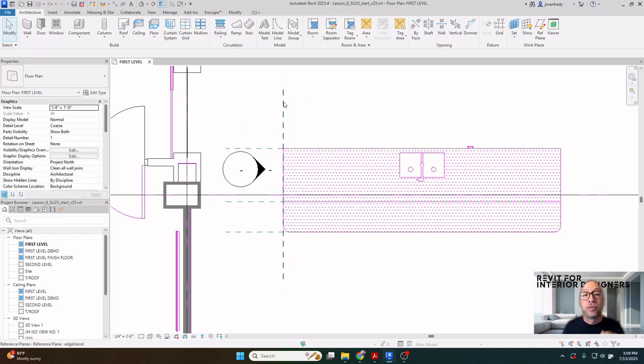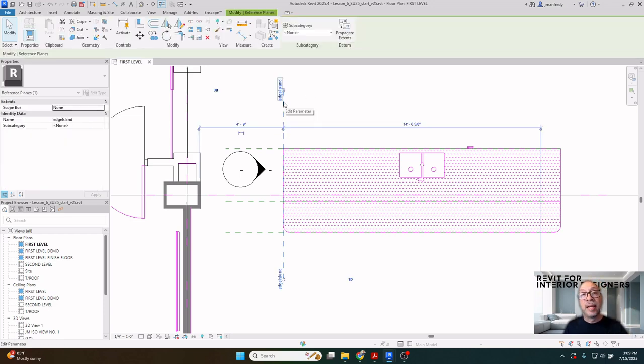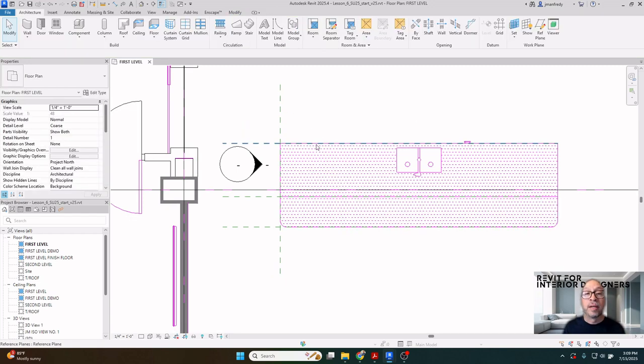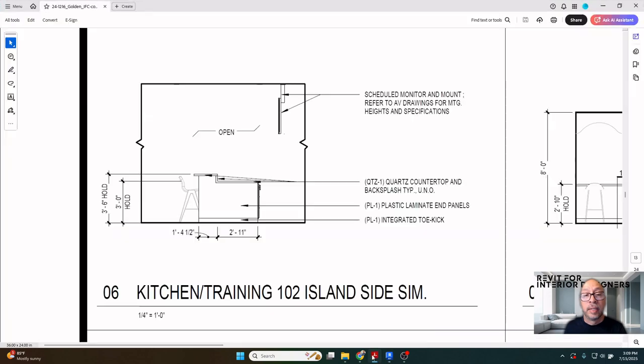And so that surface acts like a piece of glass, and I will draft on top of that surface the profile of the counter, and then I'll make it 10 feet long. So rather than drawing it in plan, I'll draw it from the side because I want this thing to be continuous, as opposed to drafting it in several different pieces. In this case here, I'd have to draw the top as one extrusion, the vertical piece as another extrusion, the top here, another extrusion. I've got 3 different 3D models when I can get it all done in one shot.